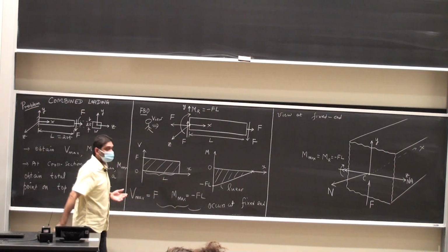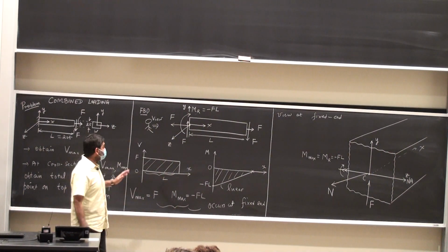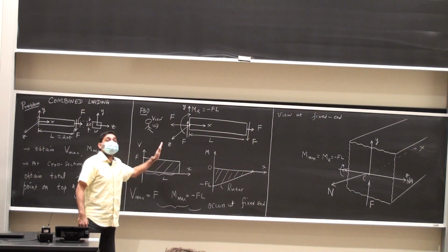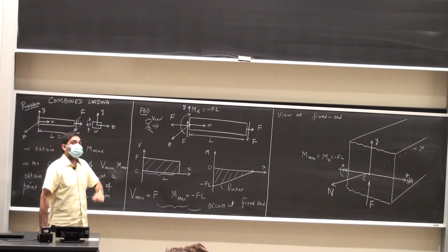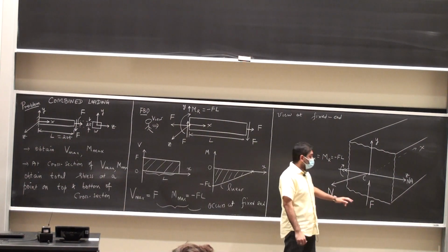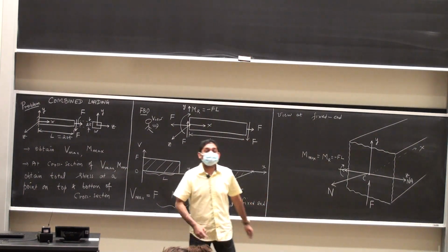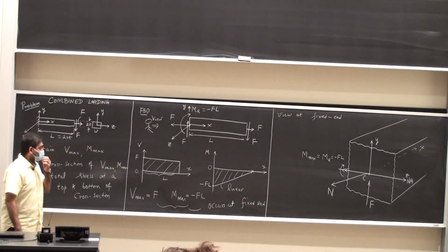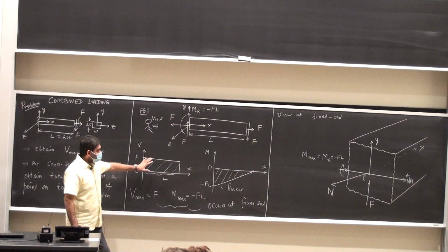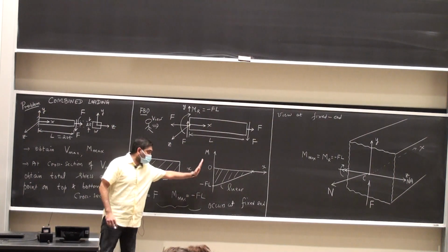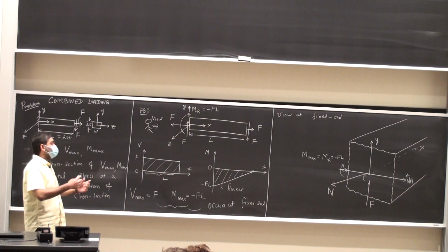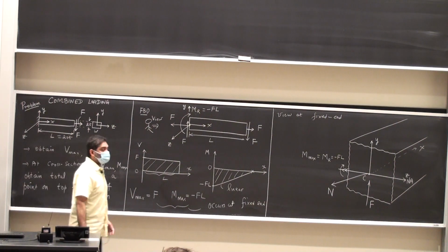You're going to be drawing out the shear force and bending moment diagrams based on the loads applied, figure out which cross section of the pipe is the weakest, and then find out due to which kind of effects the pipe is breaking. Is it because of bending stresses, or average normal stresses, or shear stresses, or a combination of all of these? That's our main aim eventually. So you draw the shear force and bending moment diagrams, figure out where the cross section contains a maximum of these, draw out a 3-dimensional viewpoint, mark all the forces, then go on our merry journey.